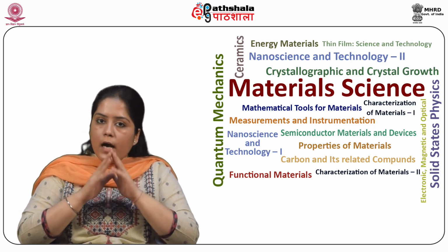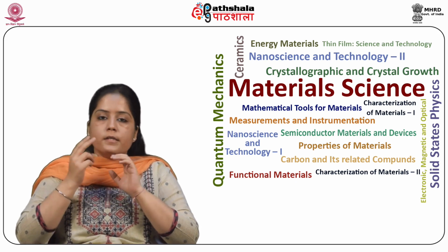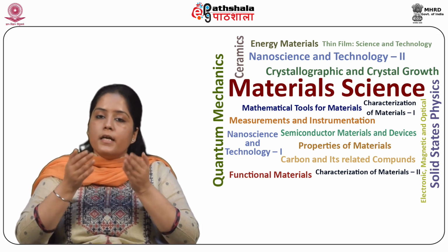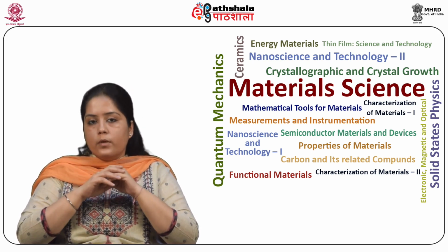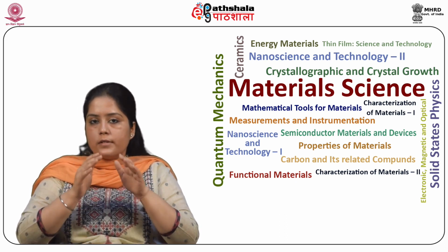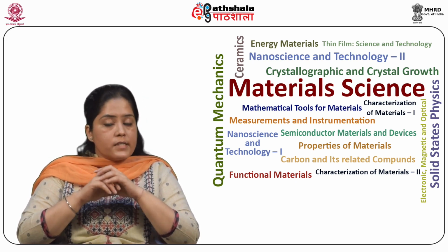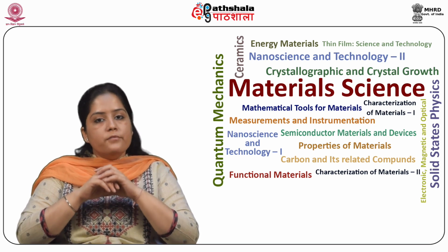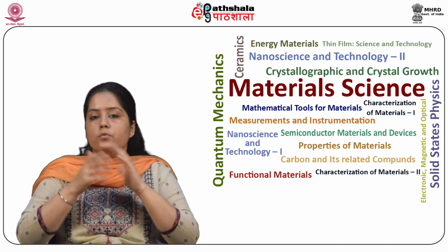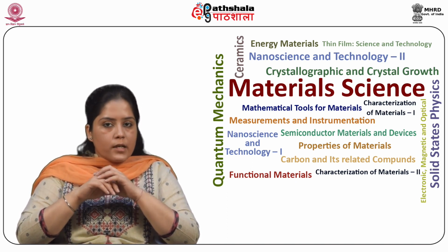It has a high degree of magnetic anisotropy. Second, it magnetizes relatively easily along the 0001 direction or c-axis of its unit cell. Lastly, it is categorized as a hard ferrite with coercivity between 50 to 100 kiloamperes per meter, depending upon the microstructure and composition.